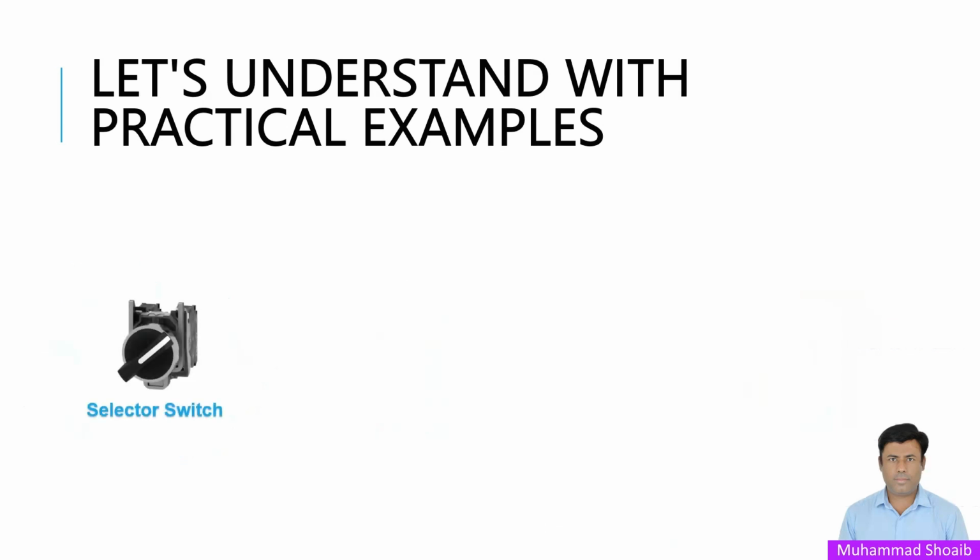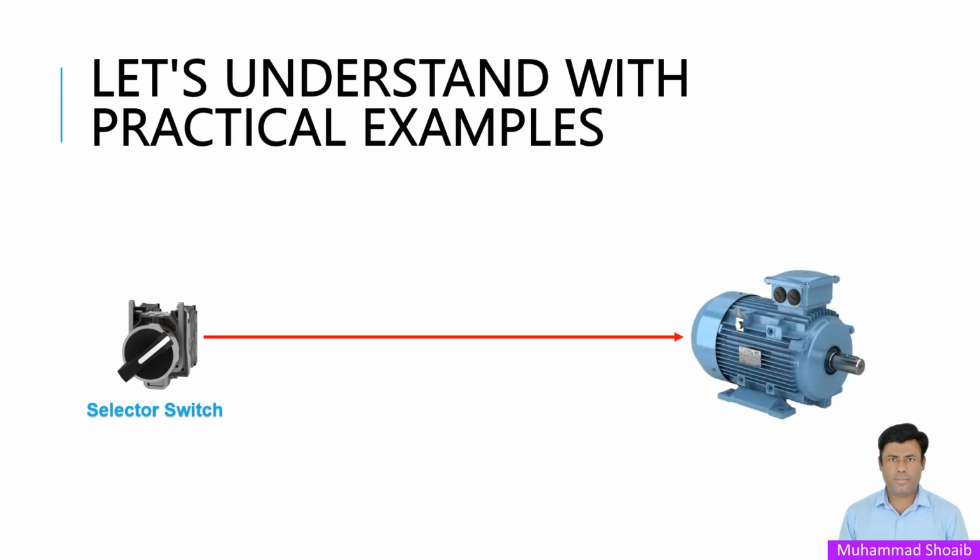For example, we have a selector switch and we want to control our motor with the selector switch. How can we program it in the PLC? The selector switch input will come in the NO contact. We will give the reference where the selector switch is connected in the PLC input. We will give the input address. As you can see here, the input address we already assigned is I 0.0. Once the selector is on or off, accordingly our NO contact will change.